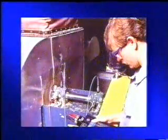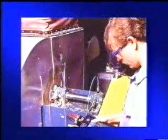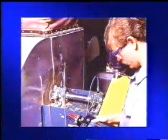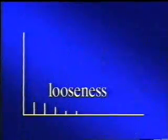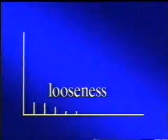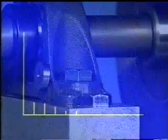During a balance job, the phase readings may be steady and then become erratic after a correction weight is applied. This is because a looseness condition existed at the beginning of the balance procedure, with the force of unbalance pulling on the rotor, holding it in a firm position and masking the looseness. Once the force due to unbalance is reduced substantially, the rotor exhibits looseness as the dominant condition, which then minimizes the effectiveness of further balancing.